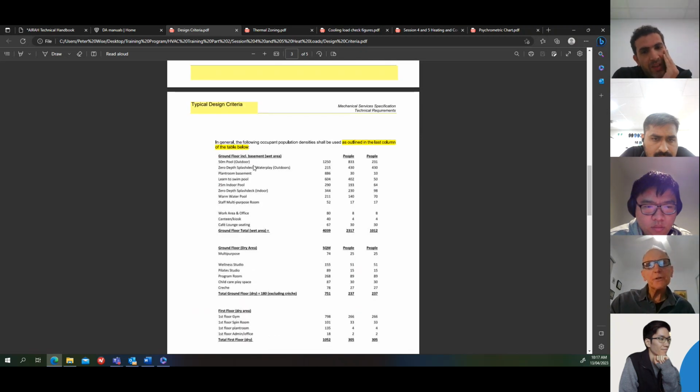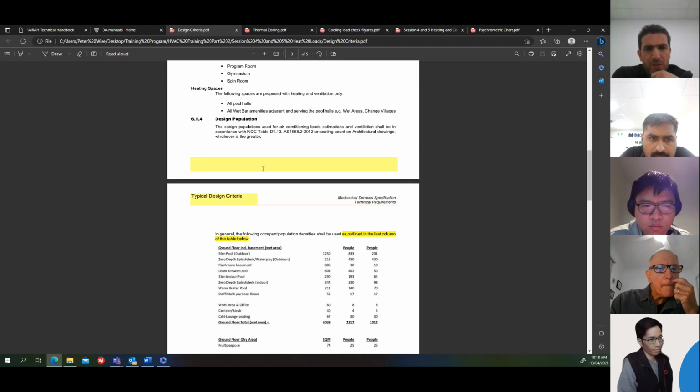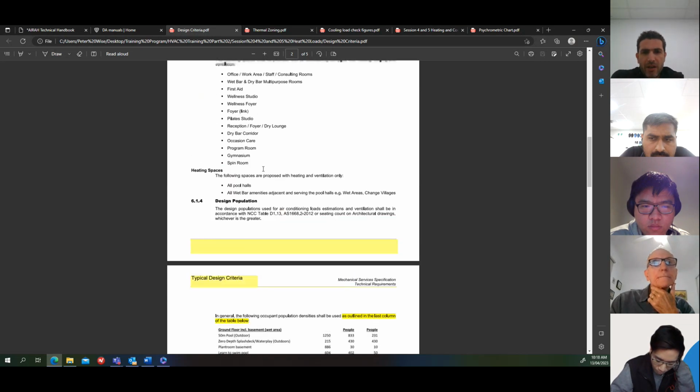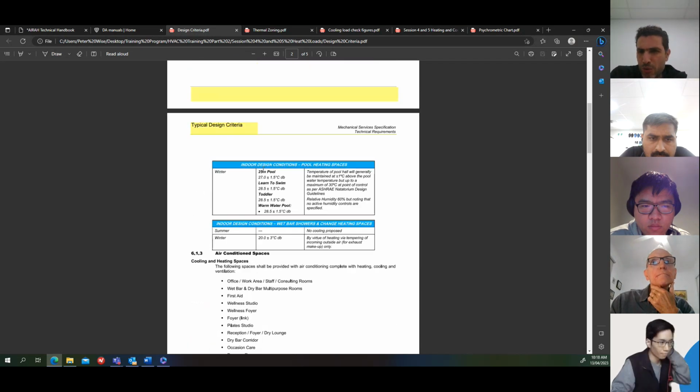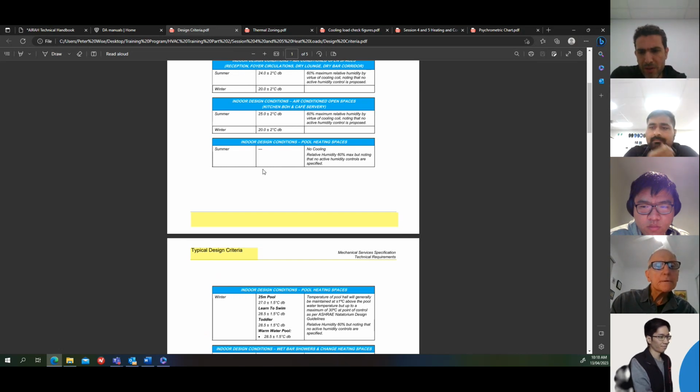For an office space, it's pretty straightforward. Can I just ask a question about the coils and the RH point where you said without controlling the RH, controlling it would be basically, and correct me if I'm wrong, playing with the thickness of the coil to either capture more moisture or not. Is that correct?